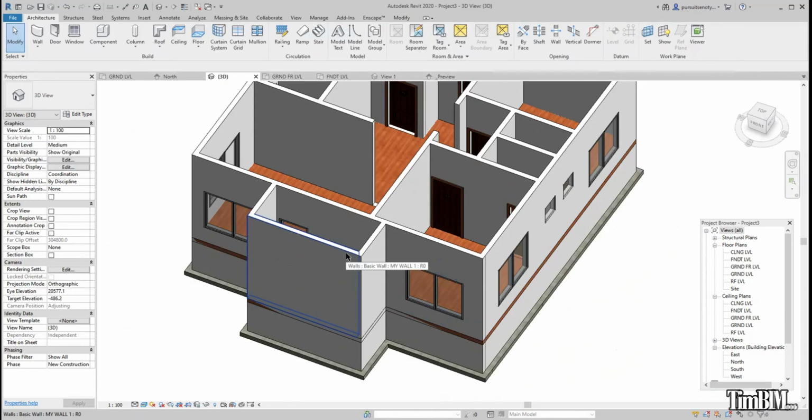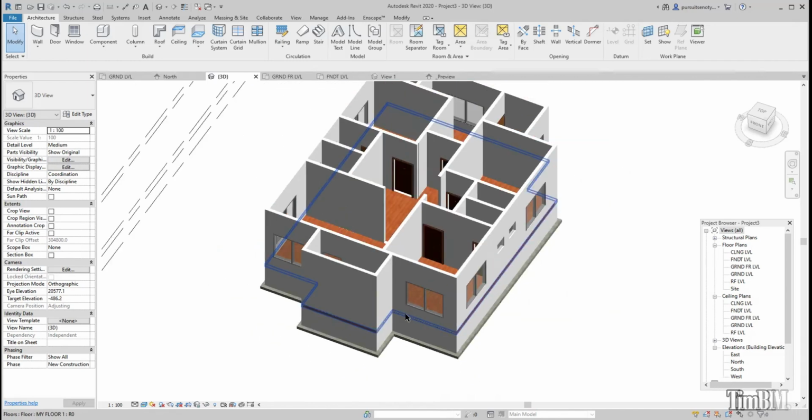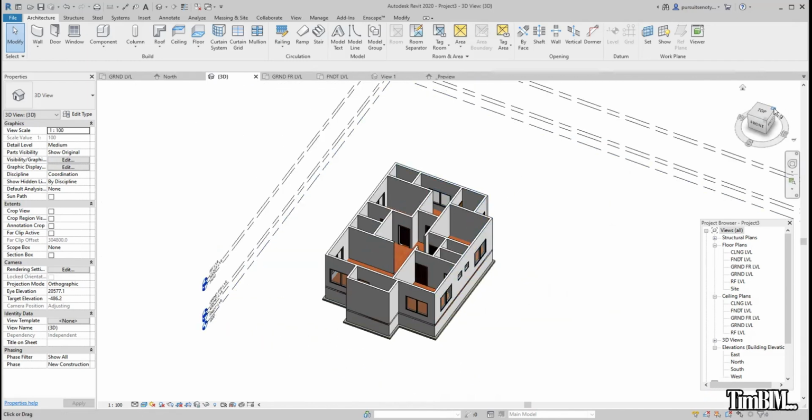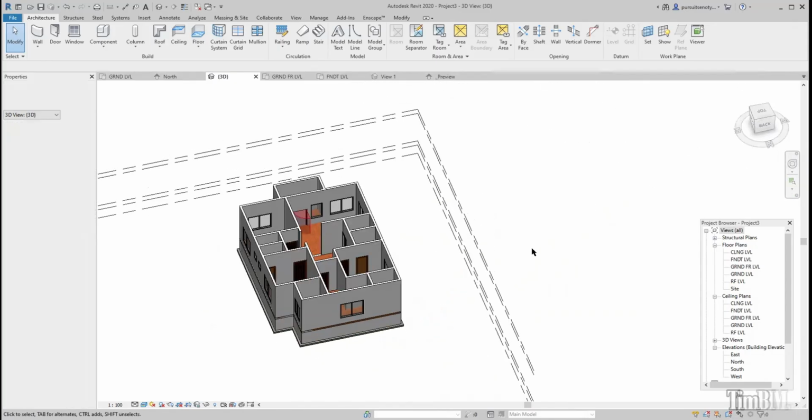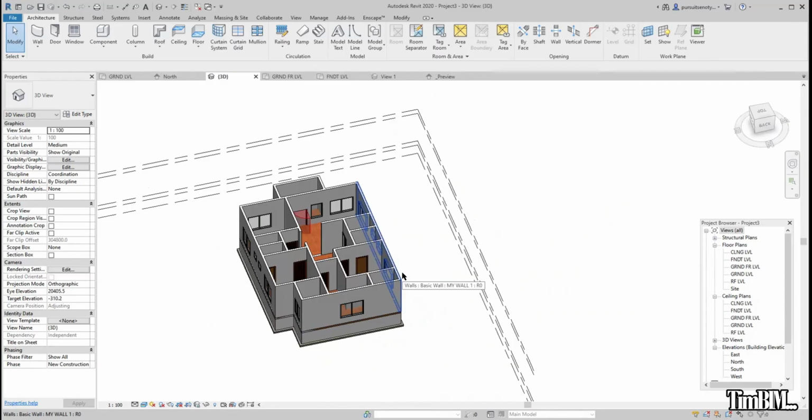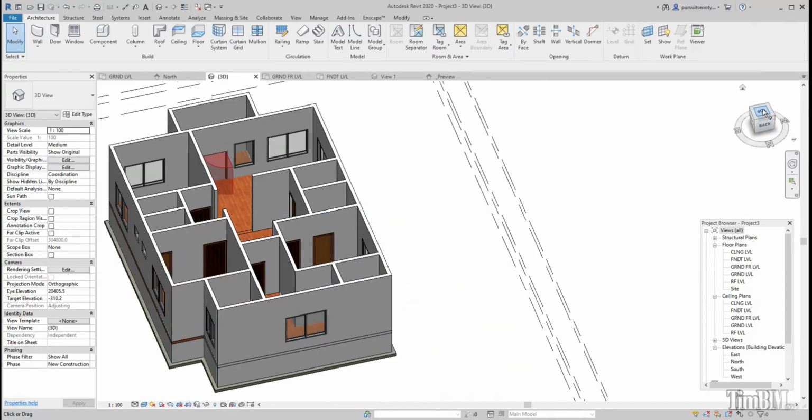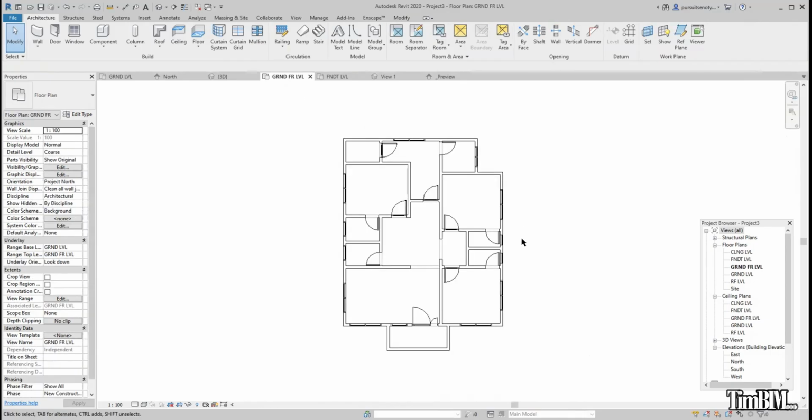After doing that, we want an opening here, opening here, or opening here. We have to create the opening. And over here also, we want an opening here, opening here, a column into the design. So we go to ground floor, come to our families, desktop, Revit. Then I go to Revit families. Then I look for our column.